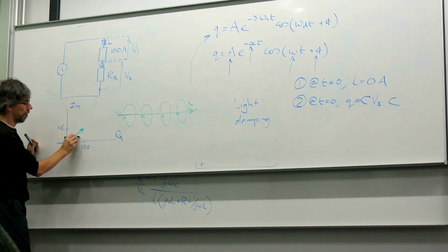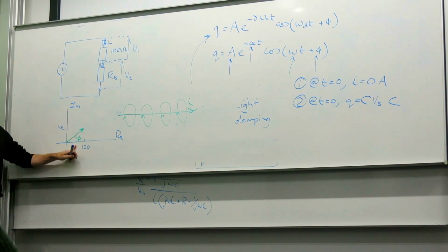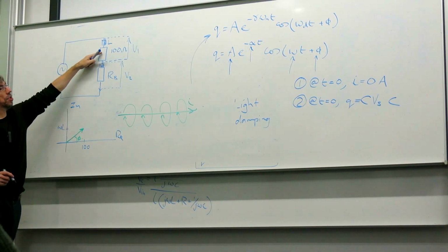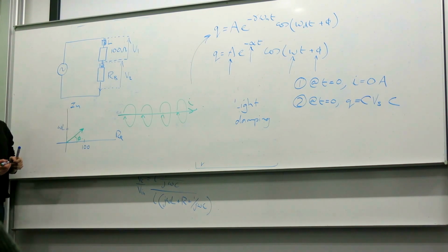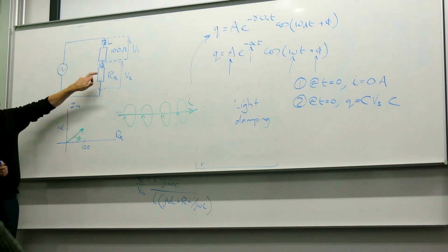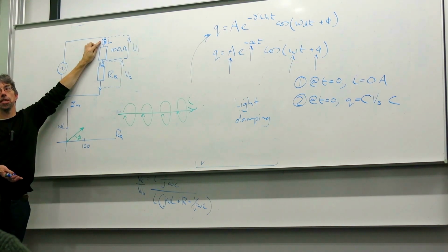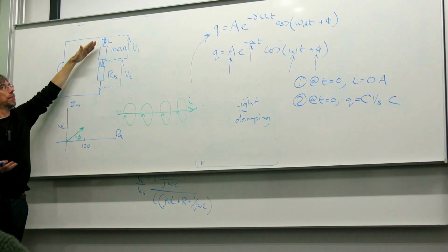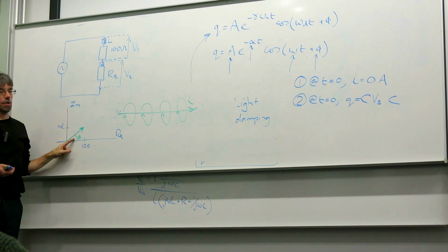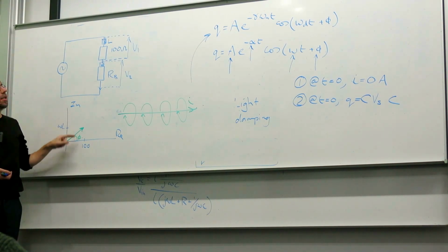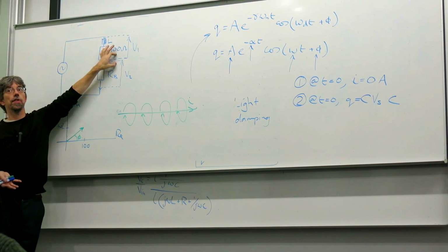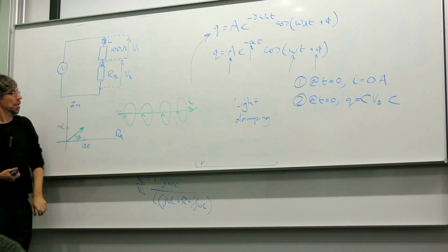So a little bit of phase angle starts to creep in between the current and the voltage. Well, if the amount of parasitic inductance in both the resistor box and the 100 ohm resistor is the same, they will both be advanced relative to the current by the same amount, and so their voltages will still be in phase with each other and you won't notice.